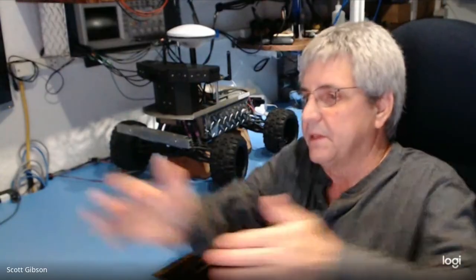Well, even with the Pixy cams, right? It starts filling up the screen, and you can't tell where the center of it is. Right. So when I get within a half a meter or something like that, I switch over to my time of flight sensors and my lidar to know where the center of the cone is more accurately. Yeah, and that's what I do on CanMan as well. I use that same kind of approach, but you only get so close with the camera. If I can get to 6 or 8 meters, the camera works good, and then I can pull it into a half a meter and then start using lidar and stuff to approach the cone.